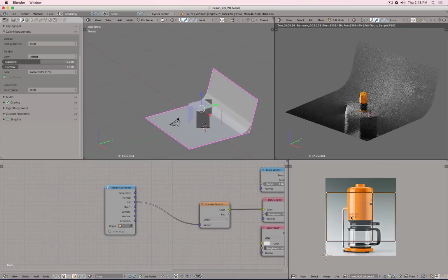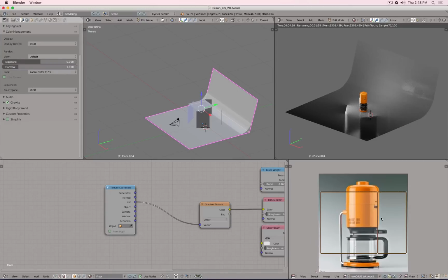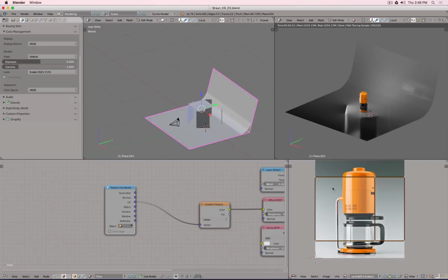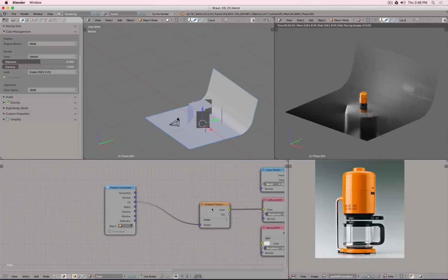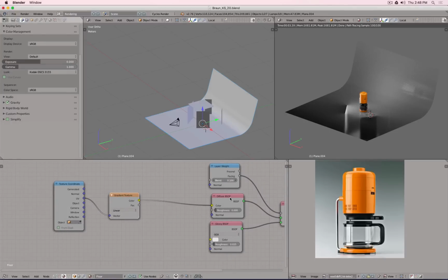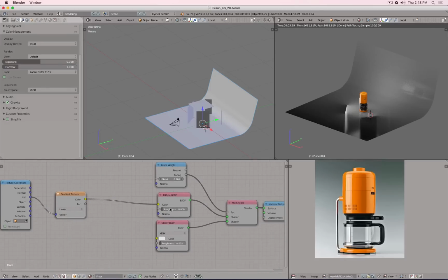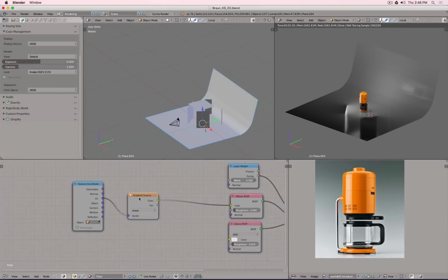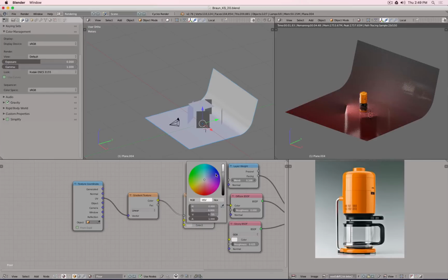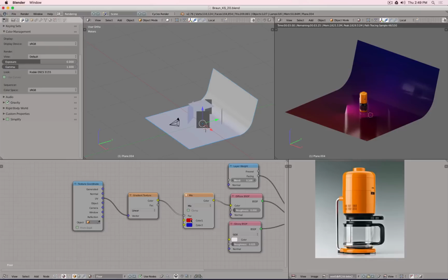Maybe let's go to there. Okay, so scale this one up a tick, and I would like actually to have now a white to this turquoise gray color blend. So between gradient and diffuse, I need to add a color mixing. You see, sometimes we mix different materials with the shader mixer. We can also mix colors with a color mixer. And that is here under color mix RGB. This goes into the factor again. So the gradient texture basically provides us with a gradient, and with this gradient we can blend between two different colors. And there we are. So this, for example, should be our white foreground.